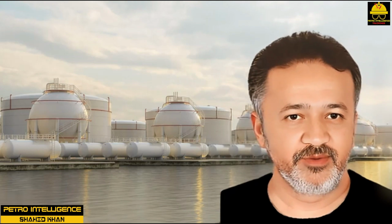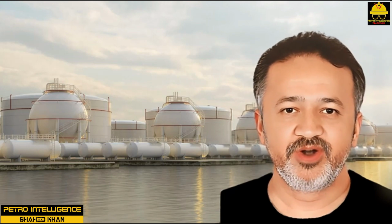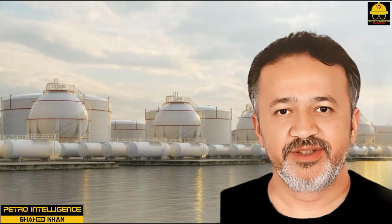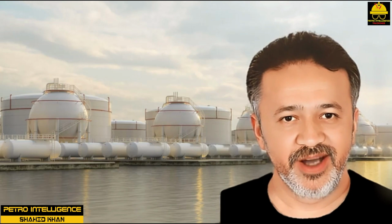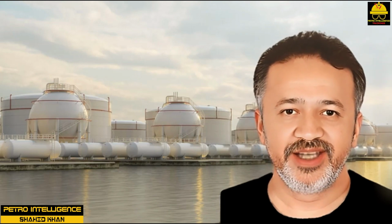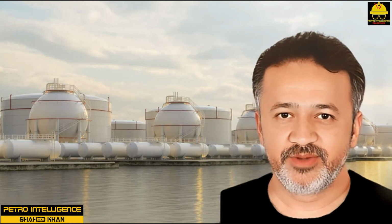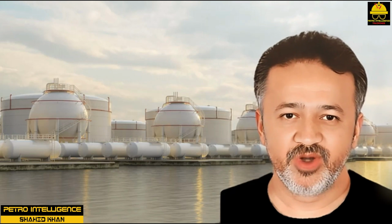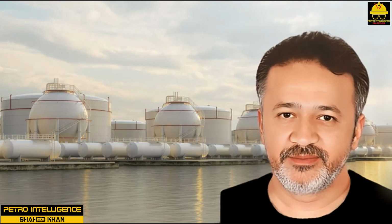The vapor dome roof looks like a cone roof tank with a hemisphere located at the center of the roof. Inside the hemisphere is a membrane of the same shape attached by its outer edge to the equator of the vapor dome. This membrane is free to hang downward in the form of a hemisphere. Hence, the movement of the membrane is equal to twice the volume of the hemisphere.